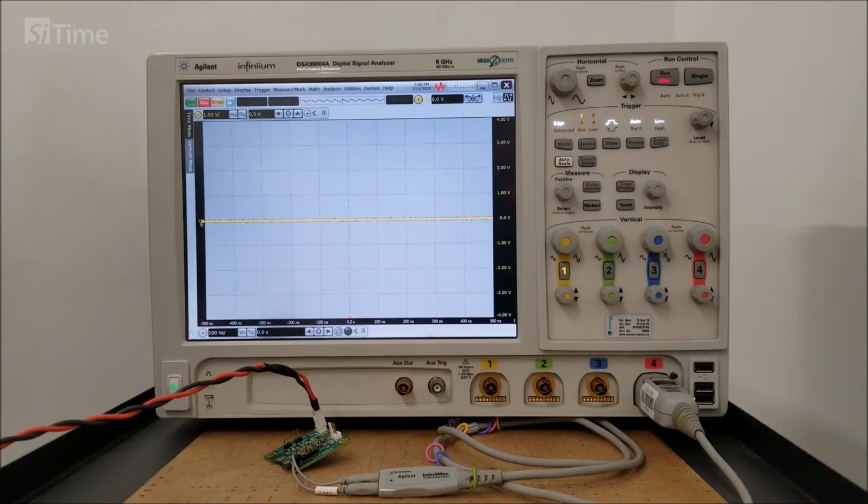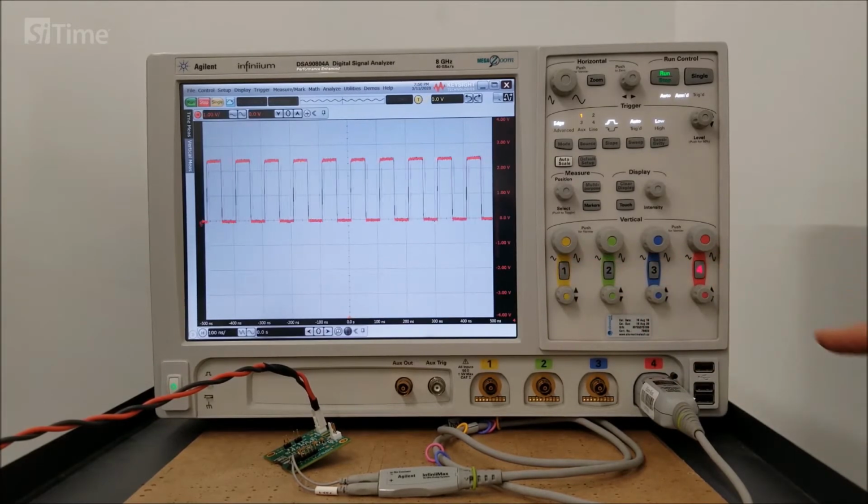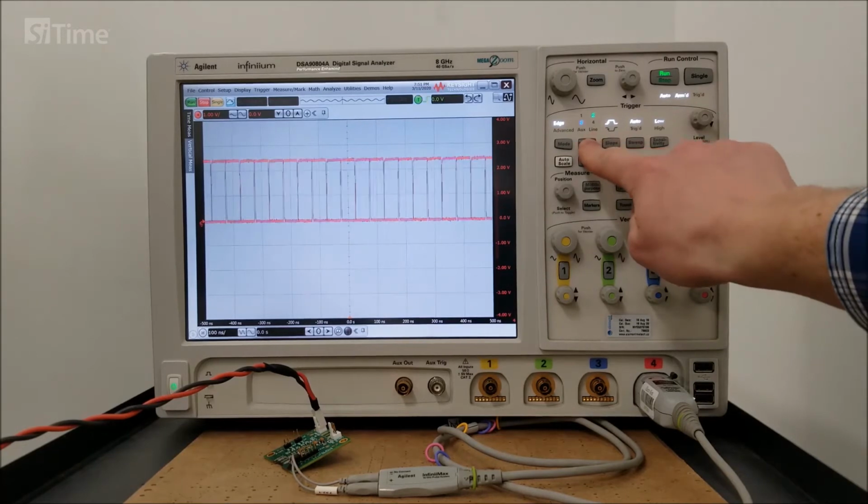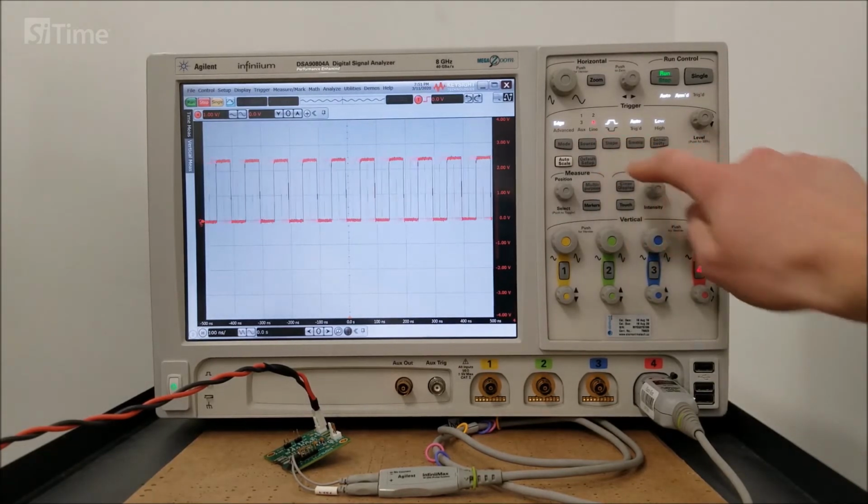For valid measurements we need to set the probe and oscilloscope properly. To start with the oscilloscope settings, let's start acquisition. Turn off unused channels and turn on the channel where the probe is connected. Let's use the same channel for synchronization and the rising edge of the signal.